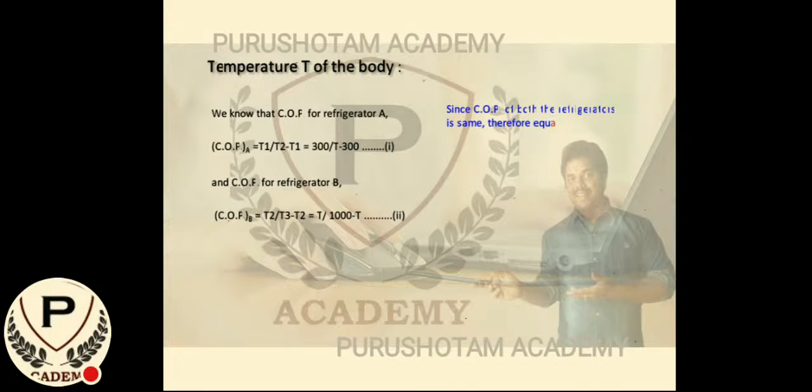Okay, so since COP of both the refrigerators is same, therefore equating equations 1 and 2, we get 300 by T minus 300 equal to T by 1000 minus T. So further resolving, we get 300 into 1000 minus 300T equal to T square minus 300T.